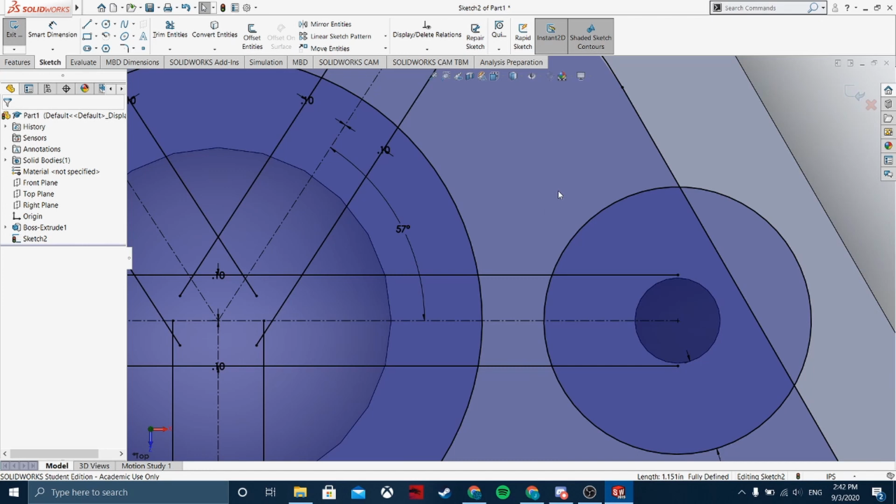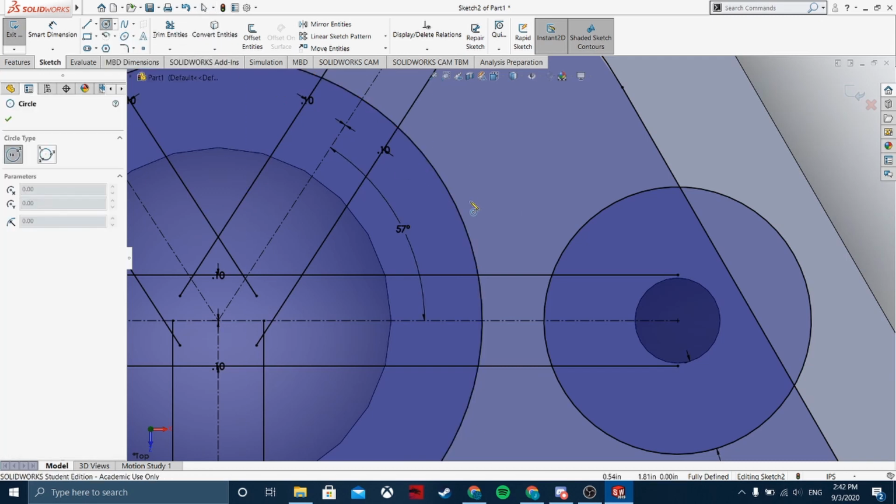And so I just want to create just one curve like this. How we're going to do that is we're going to click on circle and we're going to find, right? Okay, look, the radius is 0.12, and the circle doesn't even reach this bridge right here. That means that even if we fillet this, it's going to create that sharp edge in between the two curves, right?